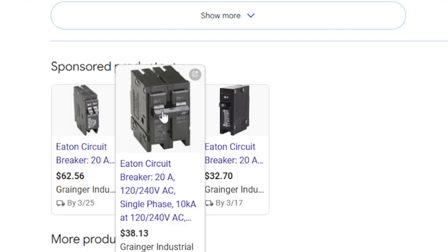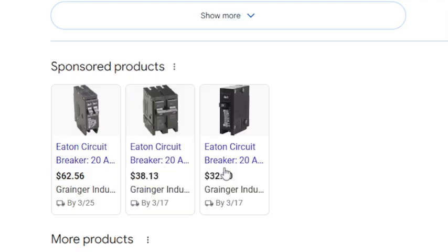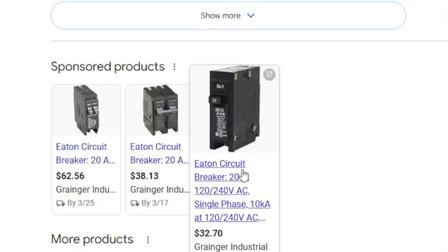And there's 20 amps. So there's a difference here. That 10,000 and that 20 amps are both protecting the circuit, just two different things. This 20 amps is just the standard rating for a 20 amp circuit. Now, the one next to it is a single pole breaker. You'll see that 10,000 there as well, by the way. This is a single pole breaker, 20, and you can see just one handle.